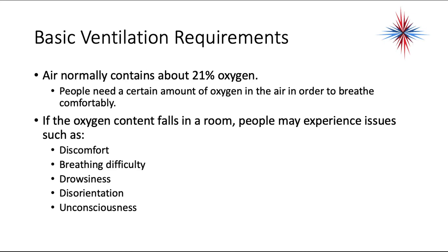We have some basic ventilation requirements. Now, ventilation means intake of outside air. Air normally contains about 21% oxygen, and people need a certain amount of oxygen in the air in order to breathe comfortably. If the oxygen content falls in a room, people can experience issues such as discomfort, breathing difficulty, drowsiness, disorientation, and if it's bad enough, unconsciousness.